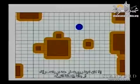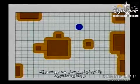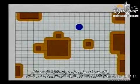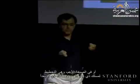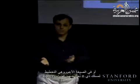If we have a several degrees of freedom robot, or we start adding orientation, then these configuration space obstacles are not only planar, like here, but become three-dimensional obstacles because you're thinking about the orientation that you're approaching with. Or you can get many-dimensional obstacles if you have many degrees of freedom. So in its more generic form, that becomes planning for an n-dimensional path in an m-dimensional space.